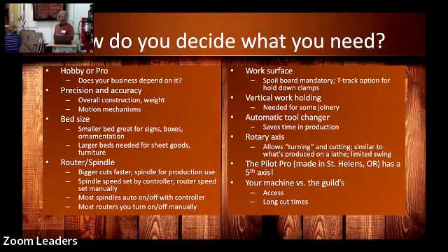The bed size, as we talked about, is really important. If you use sheet goods, you're going to want a big bed, no question about it. But if you're doing boxes and signs and ornamentation, I haven't yet reached the limits on my 2x2 bed that I've got on my machine. I'm perfectly happy with that for the time being. We talked a little bit about routers and spindles. Routers on the lower end, spindles on the high end.